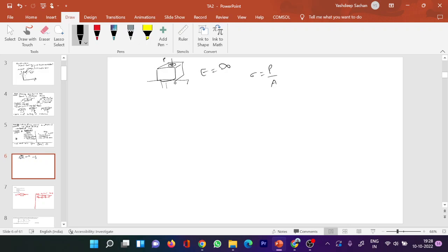Okay sir. So plane to plane the stress will change now. Here every plane's stress is going to change. Got it or not? Here stress would be different in another plane. Loading would be changed, meaning stress changed on the different planes. So here it would be P by A, and here you are saying zero area is acting, so stress would be infinite now because the area is zero. So from P by A to infinite, it will change from plane to plane if you look at it that way.